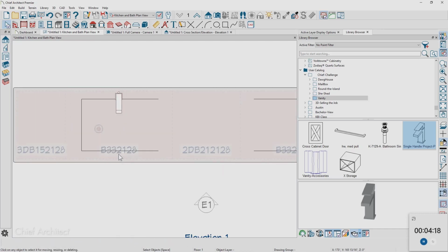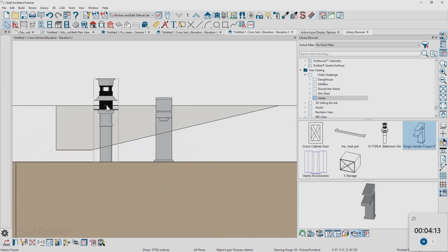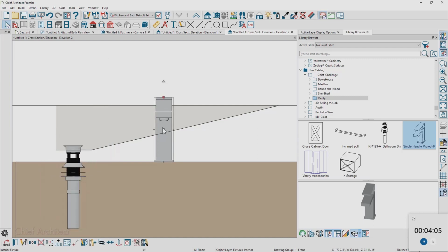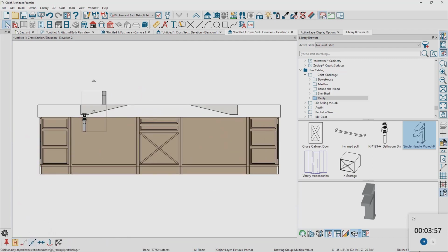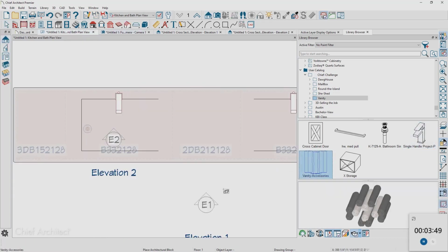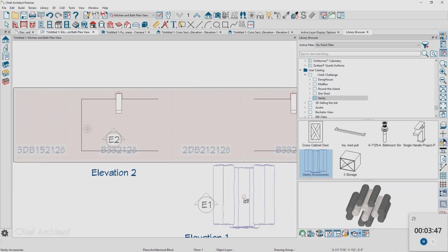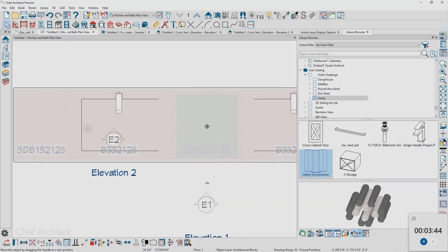And before I make a copy paste, let's make sure the elevation view is correct. So let's grab this drain and slide him down, pull him in about where we want. Same for the faucet. Let's slide that up to about where we need him. And then let's grab both. We'll use the copy and reflect about. Push that in, and then back in the floor plan view, let's grab our towels, and I'm going to hold my control key down to override bumping and pushing. And now let's go ahead and take our 3D overview and see what we got.